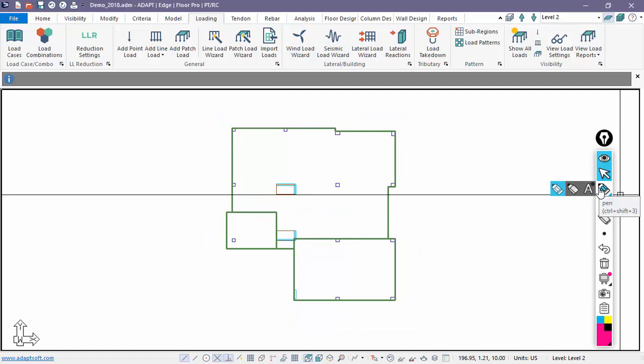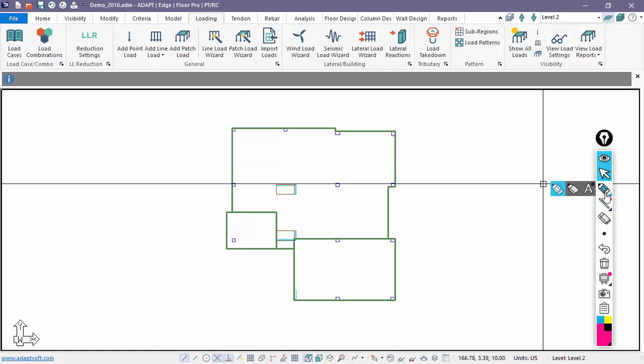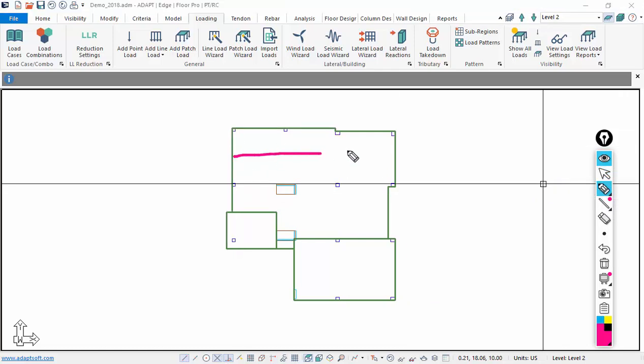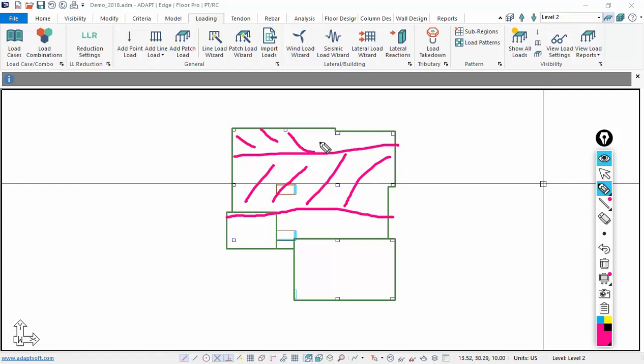So in order to evaluate the slab and to produce reinforcement for the slab, we need to break this up into X and Y strips. So we might have a strip, for example, here. We might have another strip along this path, and these are just tributary regions where we might have strips, and along here. So mainly frame lines. If you were using the equivalent frame method, you might break this into different frames, and the strips is, I guess, analogous to that type of a breakout for frame lines. So we have X, and then we do the same thing in Y.